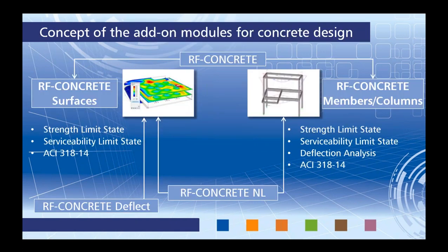So the concept of the add-on modules for concrete design. Our main program RFEM is where you're going to be doing all of your loading, your modeling. You can apply your load combinations according to different standards. We integrate with BIM software such as Revit, Tekla. And you can also run a full analysis in RFEM. So if you're just wanting the internal forces such as your moments to do your reinforcement design by hand, then by all means you can do this in RFEM alone. Now our add-on modules come into play when you're wanting to do reinforcement design according to the ACI 318-2014 and